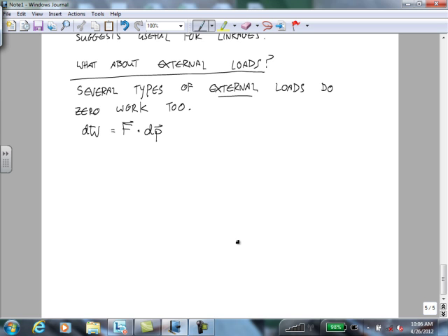And so we always put all this energy into calculating loads that we might not necessarily want at like fixed pin joints, just because we need it to complete the set of equations. In this case, like at a pin joint where something doesn't move at all, no work is done, and so we can ignore that. We never have to even deal with that force, and that's a nice benefit.